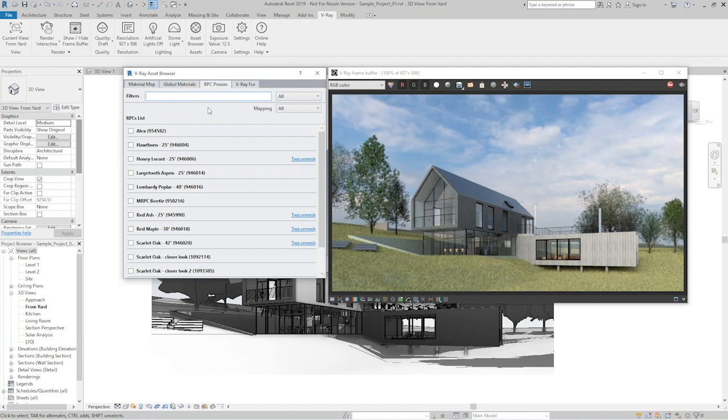And in Revit, we are unable to load proxies directly. Therefore, the RPC objects are used as stand-ins. Many users ask where to find proxy models, and actually, you can create them on your own, very easily, with the help of the Poly2VR Mesh tool. This tool comes along with the V-Ray for Revit installation, allowing you to basically turn any high poly model into a VR mesh file. Despite that it is a command line tool, working with it is really easy. I will show you now.